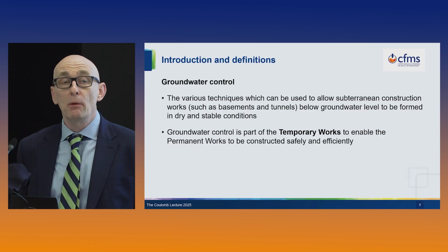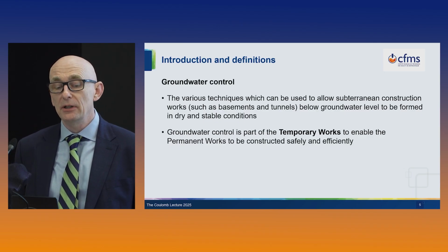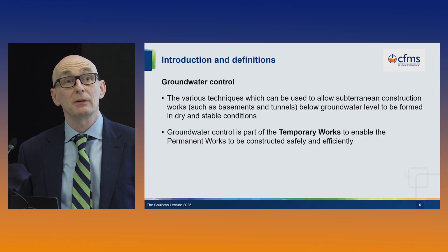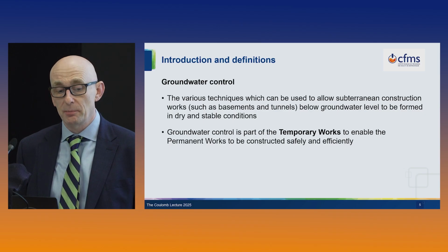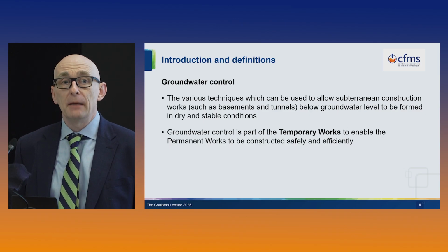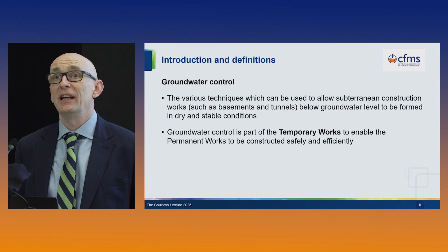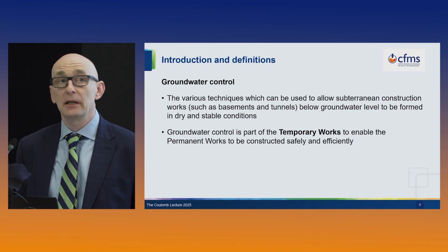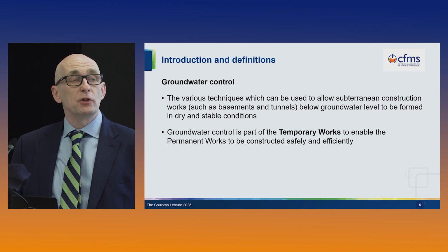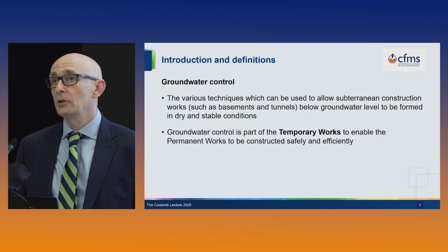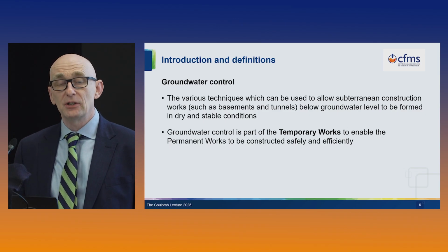So as I've said, groundwater control covers the techniques that we use to control groundwater to allow us to work in deep excavations below the groundwater level. Importantly, groundwater control is part of what we call the temporary works. In other words, it's an element that is essentially needed to produce the permanent works, but doesn't necessarily leave anything physically behind itself.